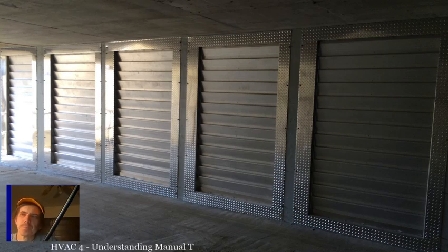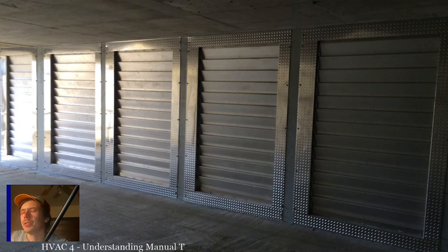When a natural draft appliance first starts up, it's not drafting because the flue has to get hot. The draft is caused by the stack effect, which is that cooler air tends to drop and more warm buoyant air tends to rise. Heat doesn't rise, but warm air does rise. So the warmer the air, the more it rises. You create a stack effect as the flue gets hot.